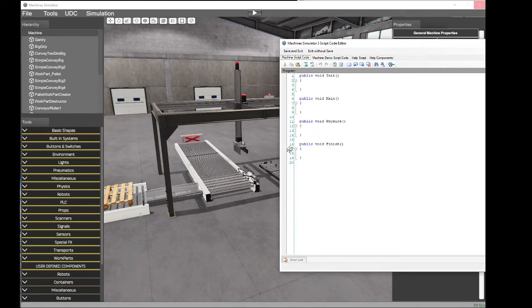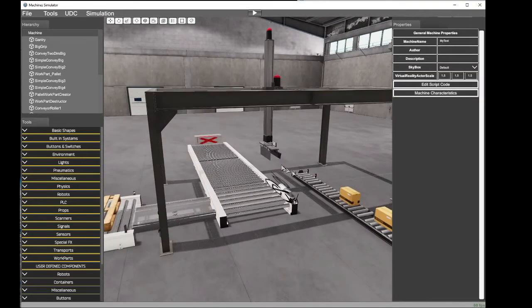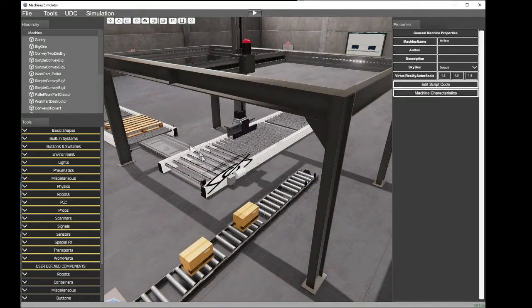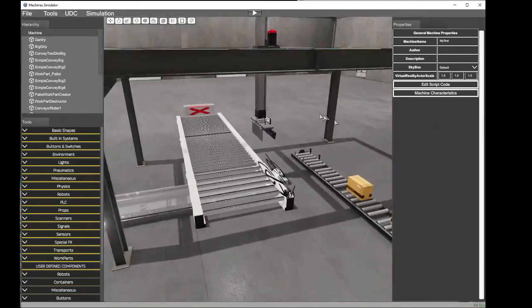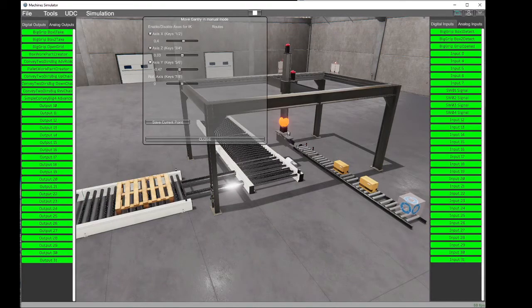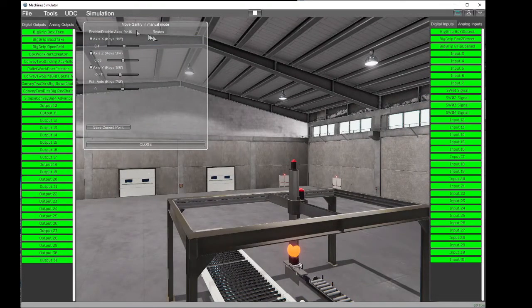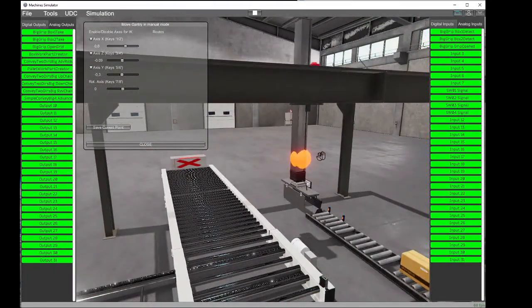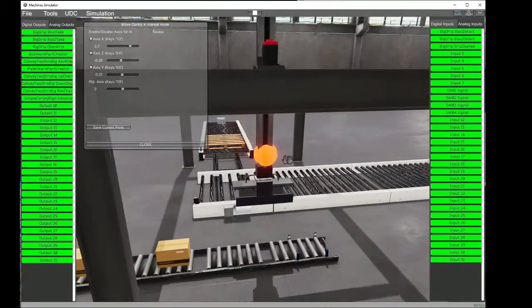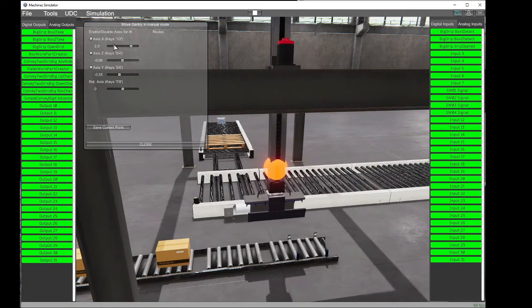Okay. To be able to write the program, we need to know what are the positions the gantry must go to take the parts and download the boxes in the proper positions. We can work in the gantry in test mode in order to move manually the gantry. We saw the window to move manually the gantry, and the glow sphere will appear. We can move with the mouse, or we can move with the keys 1, 2, 3, 4, 5, 7, 8 to move with more precision.